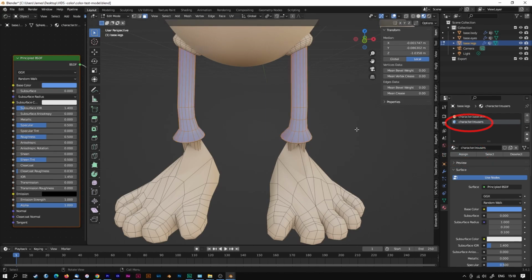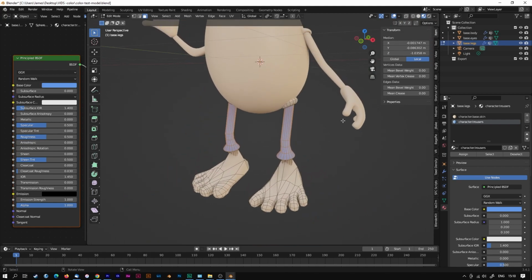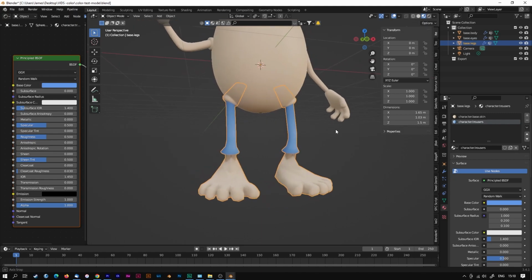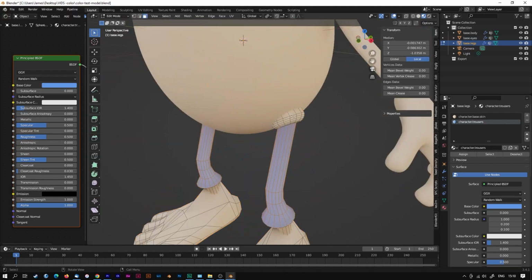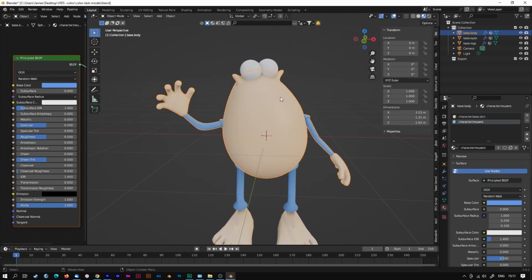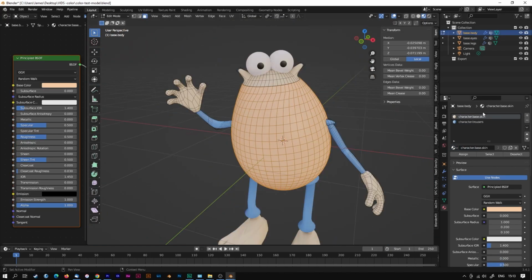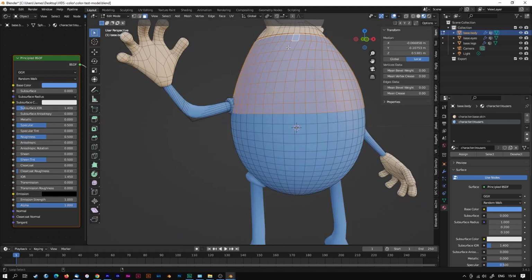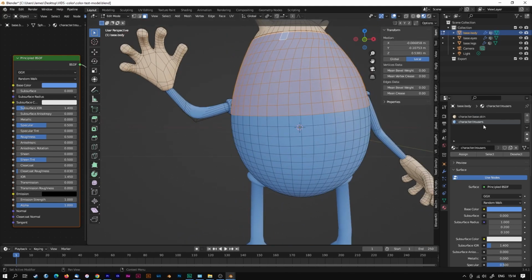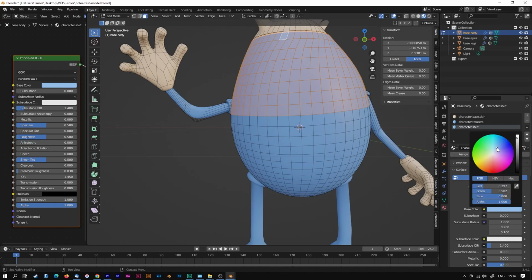To fully appreciate these changes, take your mouse's cursor over to the 3D viewport and hit Tab to come out of edit mode. To finish the colouring of this model, we can simply repeat this process until all colours are in place. Don't forget, if you want to create a variant of a color, simply choose the initial color from this drop-down and then duplicate it here. You can now tweak your duplicated color.